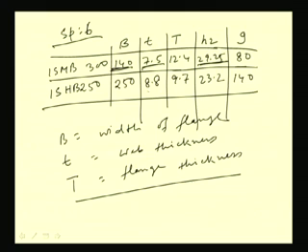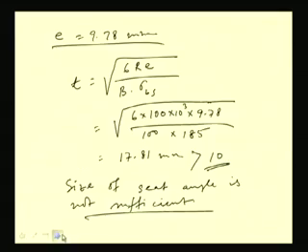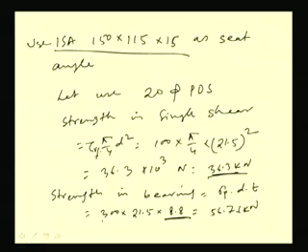If we see the earlier, this t, the web thickness, is 8.8 for ISHB 250. For the column, the web thickness is 8.8. So the strength in bearing will become 300 into 21.5 into 8.8, which is becoming 56.76 kilonewton. Now, the rivet value will become the least of these two.